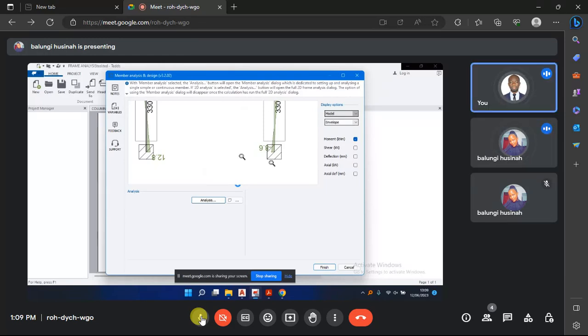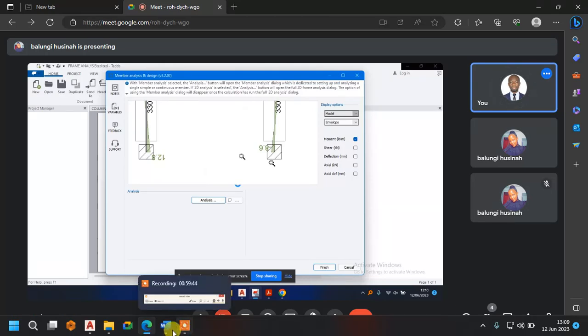So we shall use these ones in the analysis. Though the base also needs in the X and Y, but we can provide in one direction since our column was not actually stressed. So it is 12.8 and 8.6.